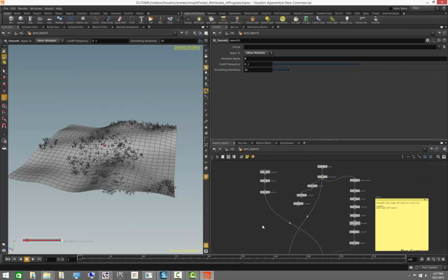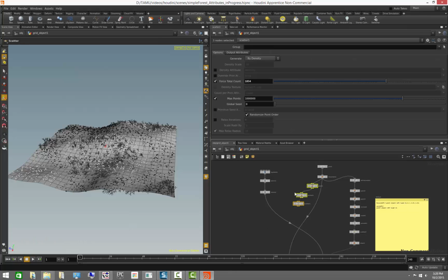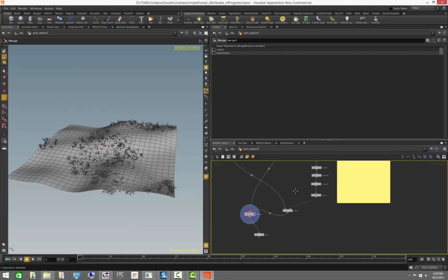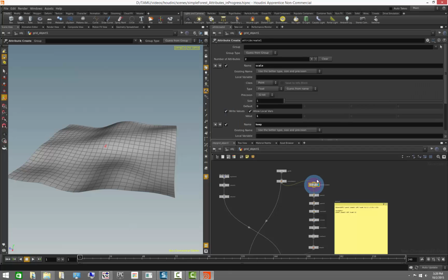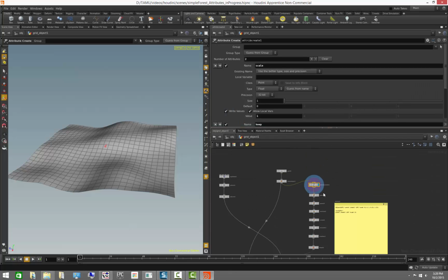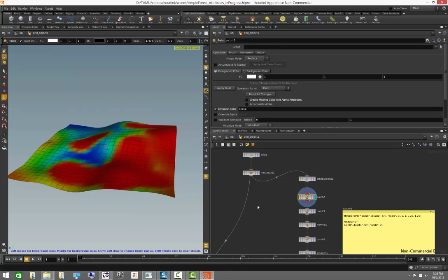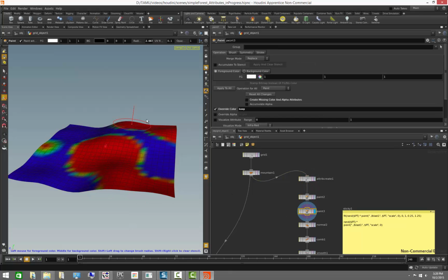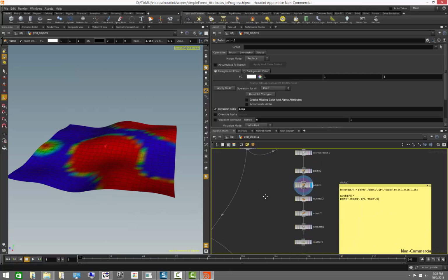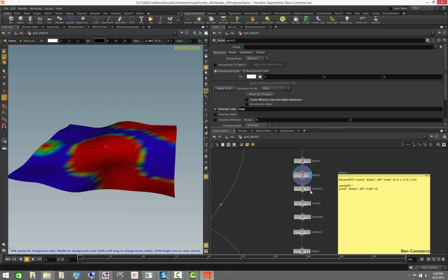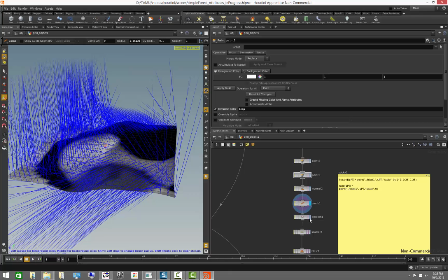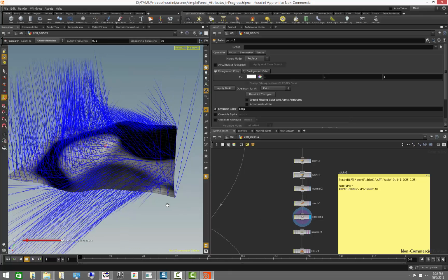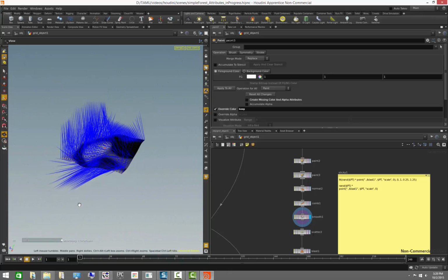Very cool. All right. So I think that probably covers it for today. So just to recap, and I'll delete the notes that we don't need anymore here. What we learned today is that we can create attributes, which we did here. We created a scale attribute and a keep attribute. We came here and painted their values in the canvas to give some user inputted values into this. We created a normal attribute here, and we're able to convert using the comb sub, as well as smoothing it using the smooth sub, okay? To give direction to the trees.